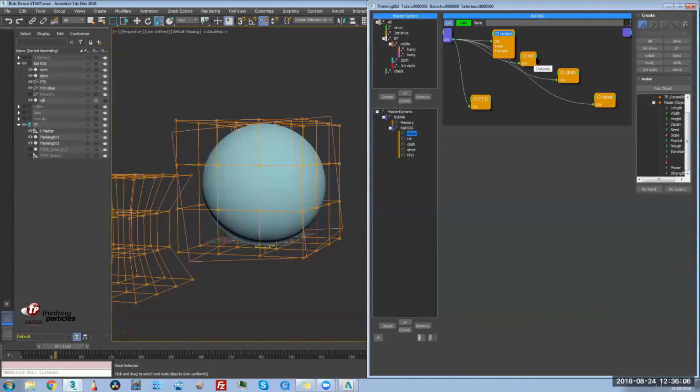So we go to the other elements. On the roll, we want to control the radius and the Z position. Basically, we want to have the Z position for all of the elements, but the noise. So Z position for everyone, and a radius and segments for the 2 drive objects, so the drive and the cloth.